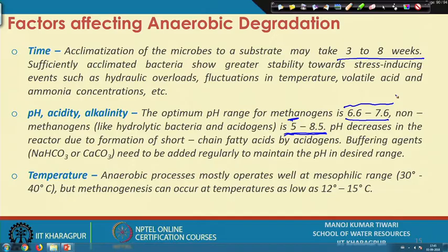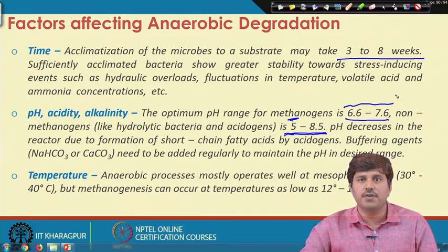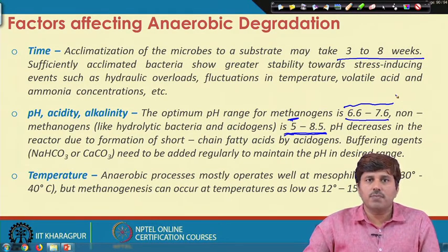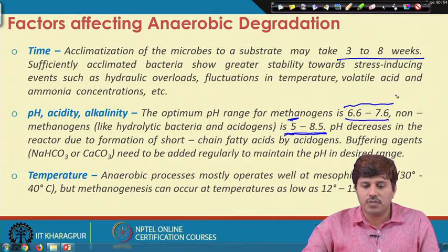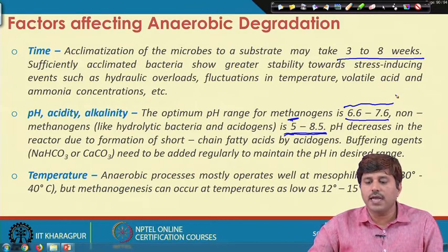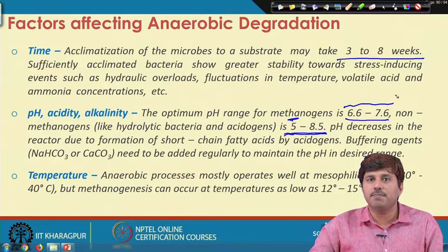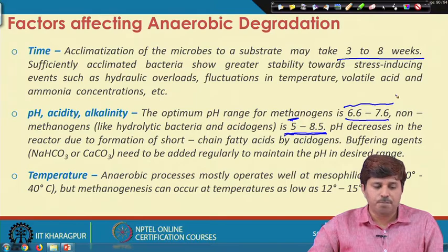So, there is a requirement of a buffering agent in the form of sodium bicarbonate or calcium carbonate that can be added regularly, so that we can maintain the pH at the desired level, because if we go too low in the pH, the acidogenesis may get greatly affected.